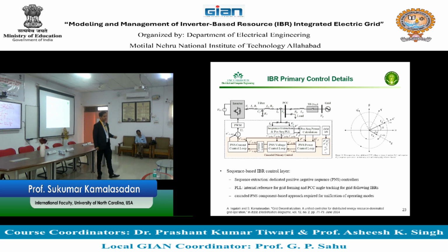So with the same capacity of the inverter, what can I do? I can do a trick. I can try to reduce the active power flowing from the inverter and use this to generate reactive current and contribute towards negative sequence. Wonderful idea, but there's a catch. I need to know what my negative sequence component is. So this sequence representation will help you understand that too, because if you are not in a normal operating condition, it will see negative sequence because you are doing sequence extraction.